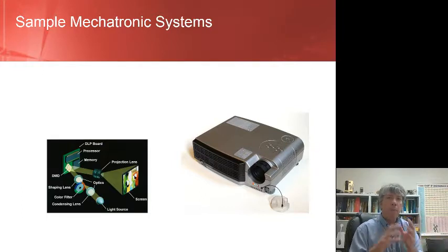If you know anything about displays, you can make any color you want out of red, green, and blue. If you look really close at whatever device you have, whether it's a smartphone screen, a laptop screen, even the old cathode ray tube screens, each picture element is actually made of red, green, and blue. Varying the amounts of red, green, and blue gives all the colors you see. If you turn on red, green, and blue completely, your eye will sense that picture element, that dot, as white. So this DLP projector had a color wheel that was constantly turning, and say you're in the red section, you'd set the mirrors so that they're reflecting the correct intensity of red light through that filter, the red channel through the filter.